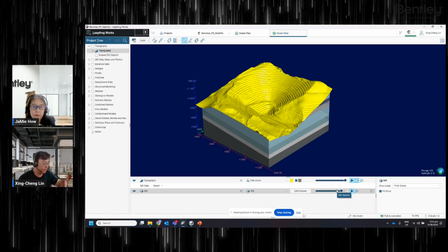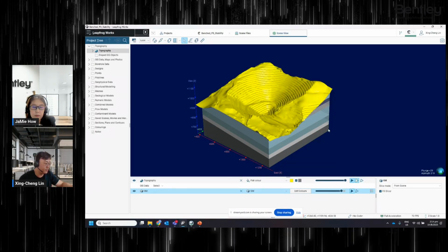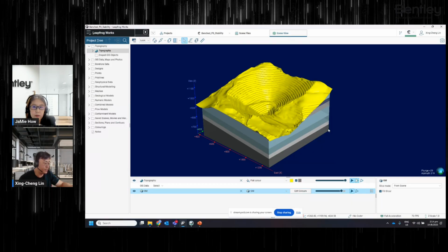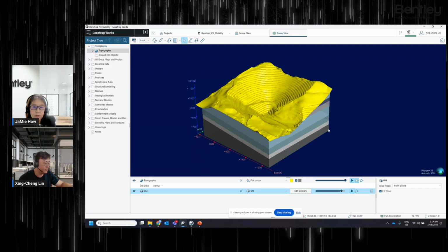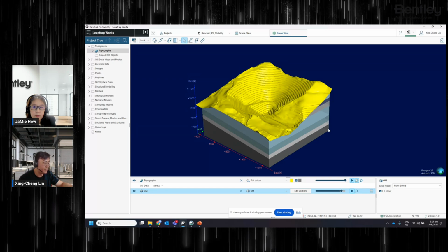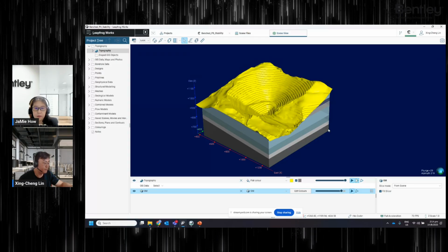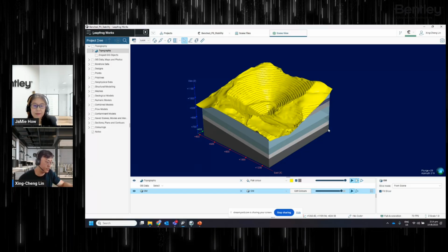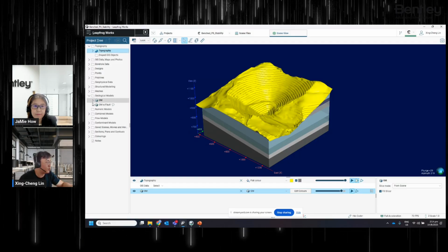So with the topography in place, we can then go into the model and add borehole data, design surfaces, points, and polylines, or those features. If we had a control section, we could include it here in the model space. You can sketch polylines on the sections and use that geometry to inform the geological model. On top of that, we can also bring in geophysical data and structural data meshes. Once we have completed it, we produce our geological model as shown here, and over the project tree, we see the various output volumes just for this model.